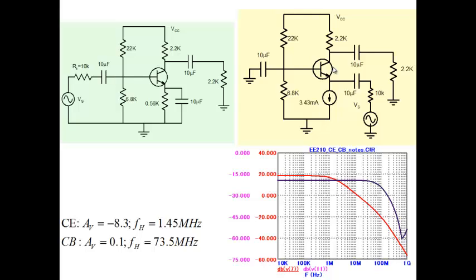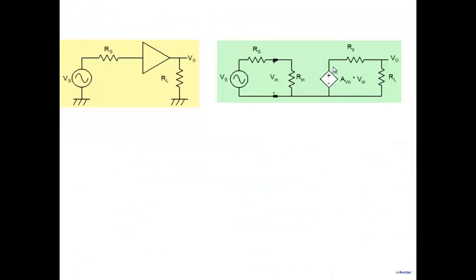Now this is where, let me see how much time I have. I'll not go forward, but I want to point out two kinds of amplifiers here. One is a voltage amplifier. Note the input is a voltage, the output is also voltage, which means your interest is in voltages. And in a voltage amplifier, what are you looking for? Input resistance to be very high and output resistance to be low, because you want the signal to go into the amplifier and you want whatever gain you have built up to go to the load. So you want R0 to be 0, Rin to be high.